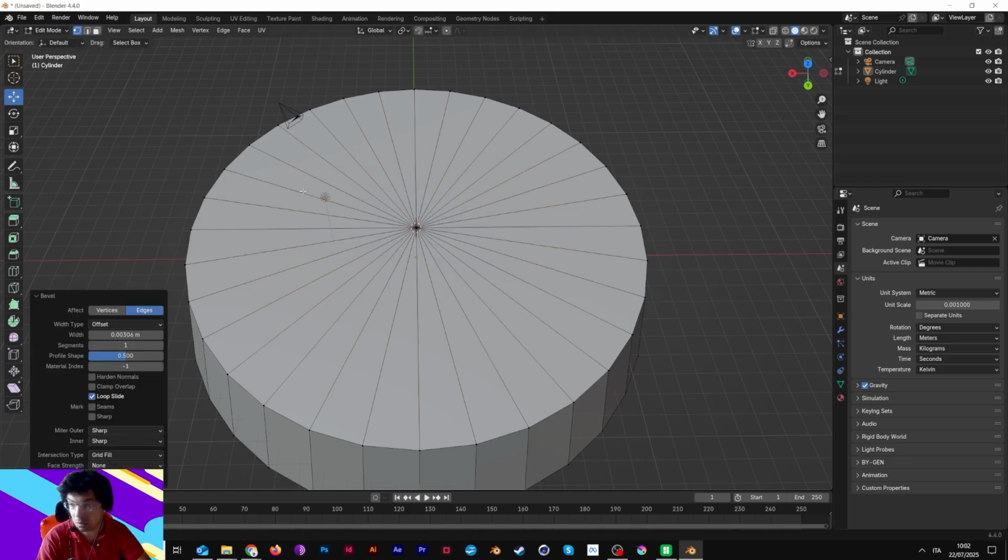Click whatever you want, bevel or bevel menu, vertices. Okay, as you can see, this is the circle we create. Just reduce it right there to 0. Oops, 0.001. Okay, delete it.